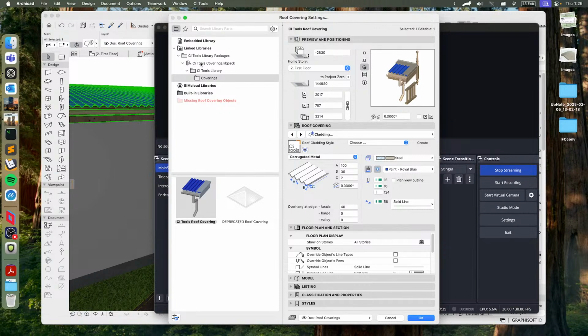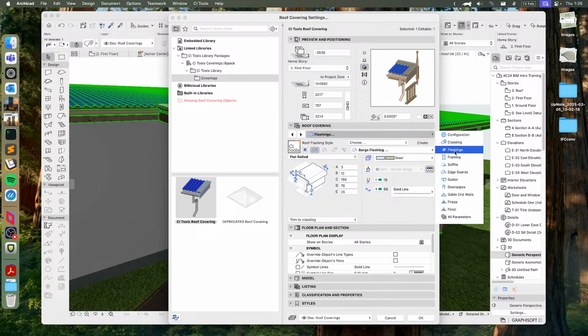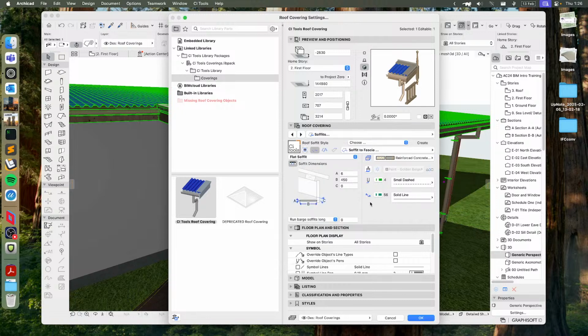One of the things that you may have noticed as we were going through the settings was that in some cases we have this little icon showing. This is the uniform button. At the moment it's pressed, and you can see that all three of these connected icons are circles. If I click this to turn it off, they will change to different shapes, and this is essentially saying that each of these three different feet types in this case can be completely different from each other.